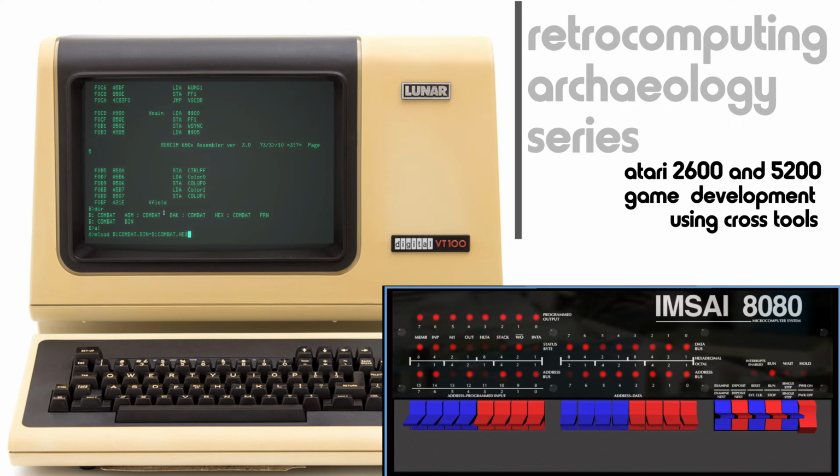This is normally used to turn an Intel hex file into a COM file to run under CP/M. But since this isn't Z80 or 8080 code, this is 6502 code, all we really need the loader to do is convert this hex file into a binary file and be done with it.